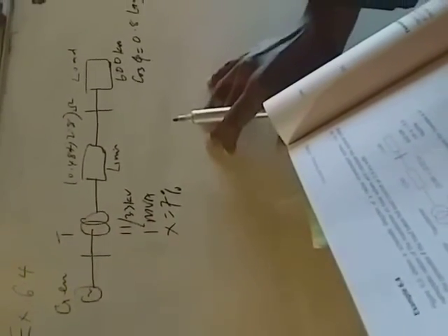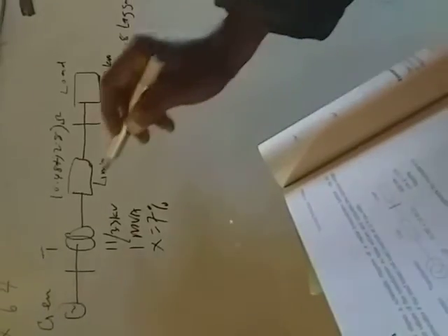This asks us to use the nameplate value of the transformer. That means we are going to use the nameplate value of the transformer as the base values. Then we must calculate the terminal voltage. We want to know the terminal voltage on the generator, if the load draws a full load current at 0.9 per unit. So invariably, what you want to do is determine the terminal voltage at the generator.